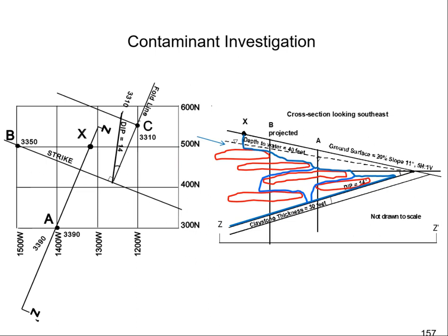Borehole A doesn't say how deep it is, doesn't say when it was drilled, it doesn't say whether it's cased, it doesn't say whether it was sealed properly. When was it drilled? 1857, you still get water out of it with a bucket. Was it drilled in 1972 by a geotechnical firm who just threw all the cuttings back in the hole and put some grass seed down and called it done? Was it drilled last week and somebody actually pays attention to the current rules and regulations about abandoning wells, abandoning boreholes? Don't know. But that's the most logical choice from the choices that we have. And directly under the site, there's no evidence for there being any breach in that claystone layer to allow contaminants to get through it.